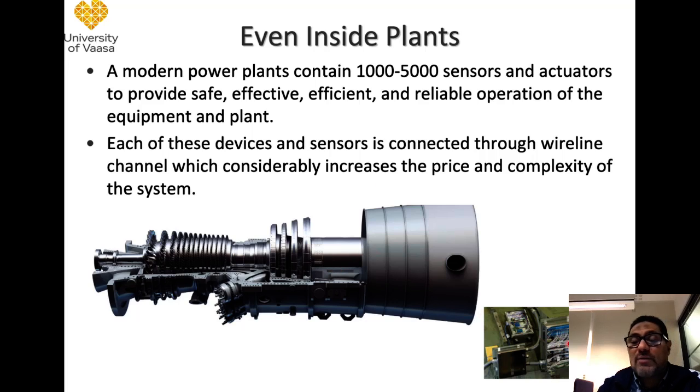So you can see that here we have wireless, but it is possible to have wireless communication, for example, inside the rotor of the motor. For example, we can embed or augment some sensors there for measuring the temperature, measuring, for example, the vibration inside the rotor, and these signals could be sent over ultrasonic, for example, because electromagnetic waves maybe are not possible because of the shield over the rotor of the motor.